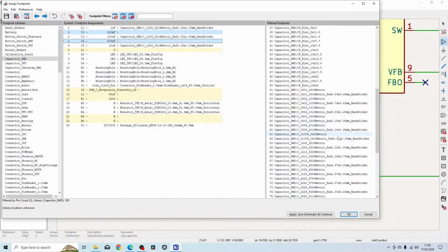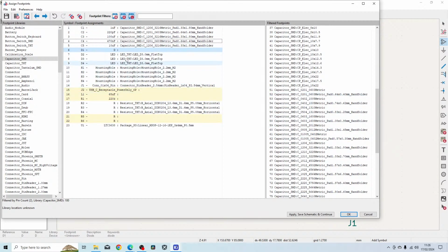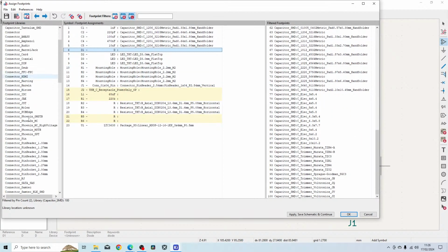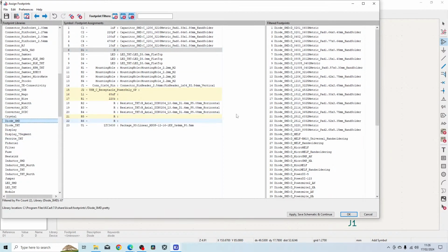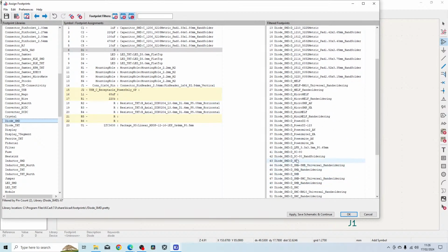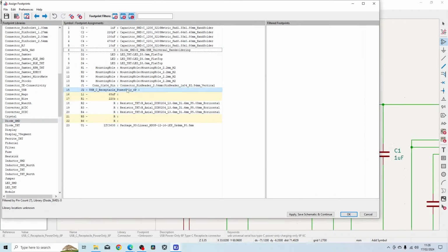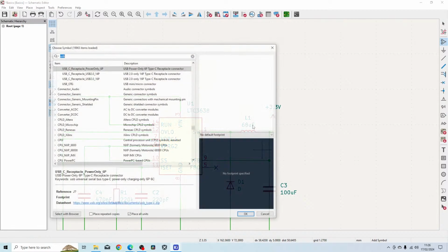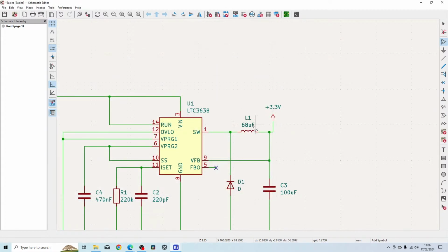These two I should be able to get in 0603, no problem. And the diode, let's see what I can find. I think generally speaking, you can just get an SMA one. It should be alright. I'm not going to go into too much detail here. 68 microfarad. Farad? Did I put farad? Well, that's a bit silly.